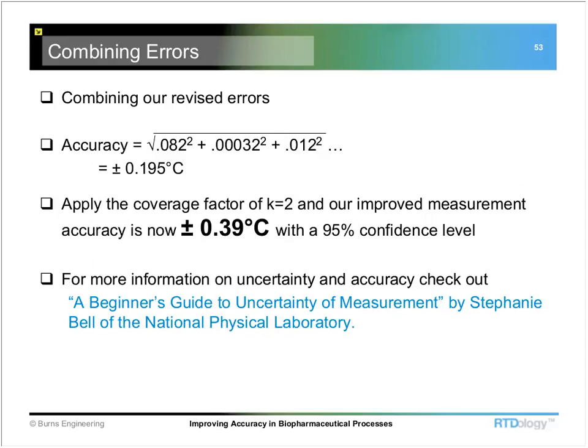So there's a lot that goes into this, and looking at each one of those error sources, it seems like every application is a little bit different. Everybody's got their own situation that arises. I was talking to somebody a couple days ago. They had an incubator where they were seeing between a 3 to 5 degrees C error, and it was reading warmer than it should. And right away I think, okay, this is an installation problem. An RTD cannot fail that badly, usually without failing completely or being erratic.